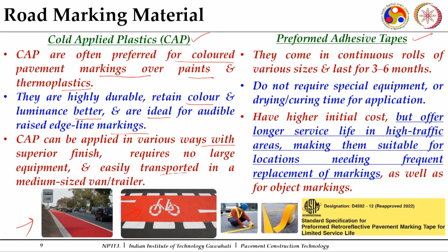Now the other category is preformed adhesive tapes. These are again some specific applications, and we have the ASTM codal guidelines also existing for them. They come in continuous rows of various sizes, and typically they have a life of around 3 to 6 months. They do not require any specific equipment, neither do they require any curing and drying period as you have in case of thermoplastic paints or waterborne or solvent borne